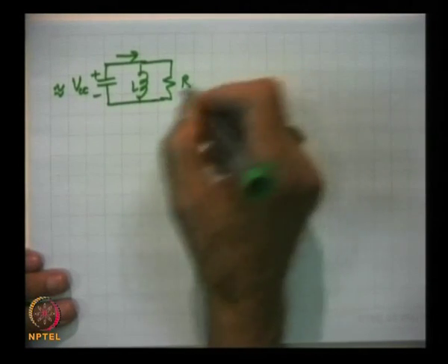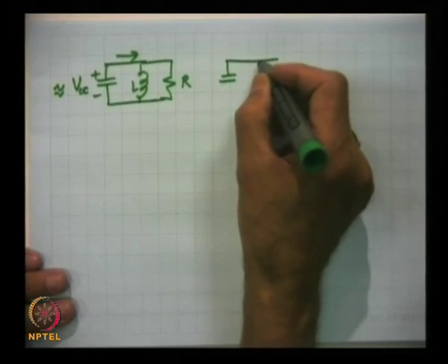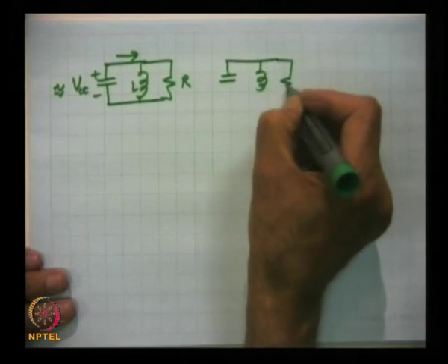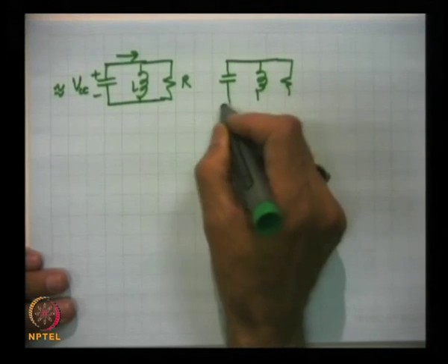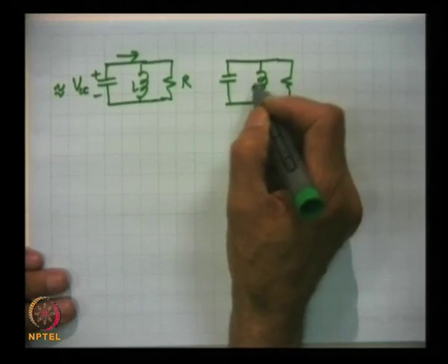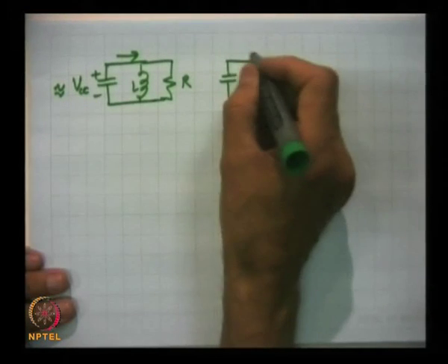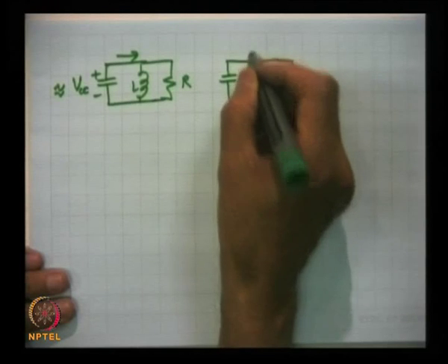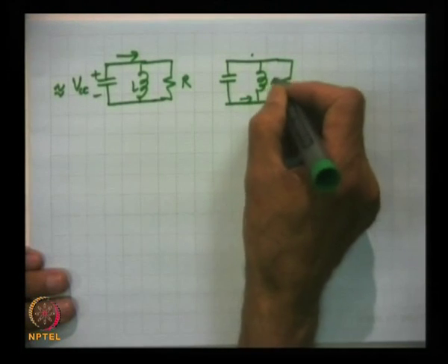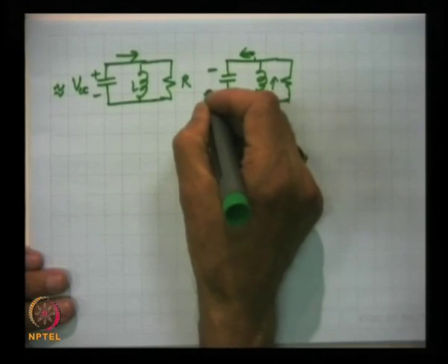The capacitor will be charged from the current flowing through that magnetic energy stored in the coil, which will send current in the opposite direction, and the capacitor will be charged with opposite polarity.